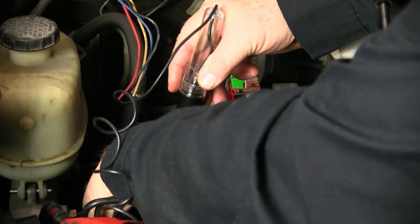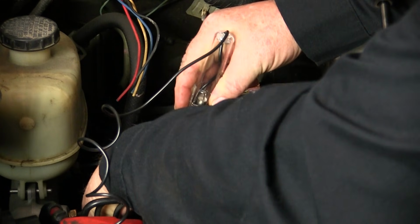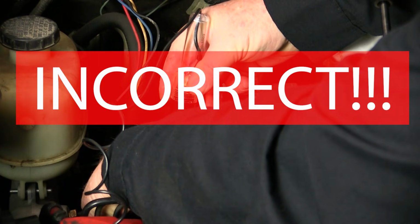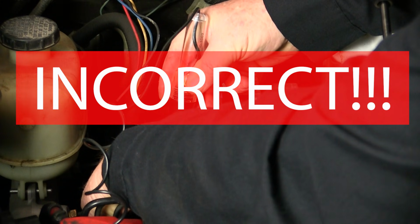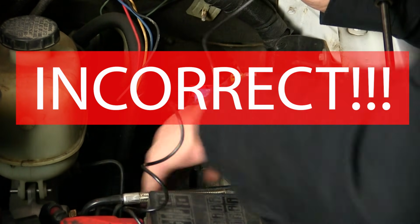And the only way to properly test for this is by checking voltage drop in the circuit. Testing with the connector unplugged and using a test light is not conclusive, and it could result in an expensive comeback if you replaced a module that wasn't defective simply because your testing method was.